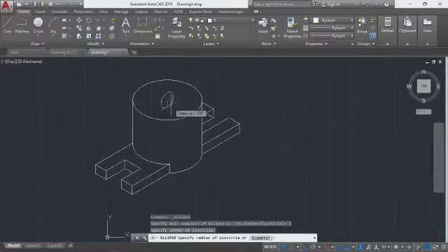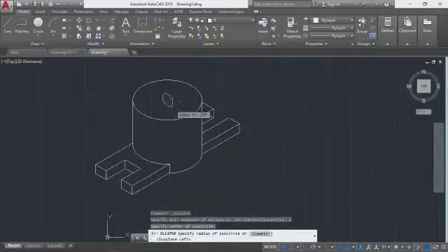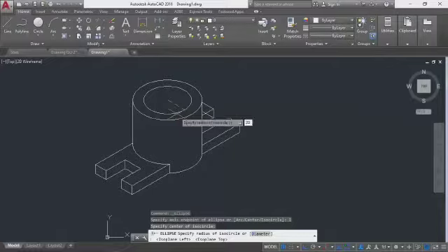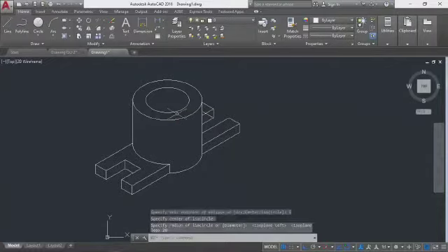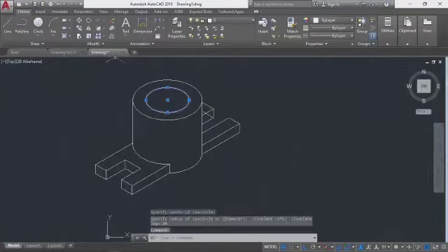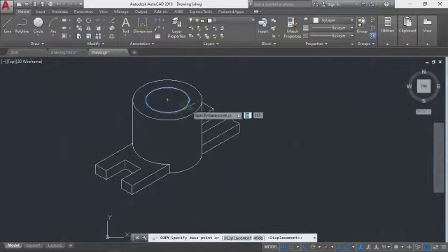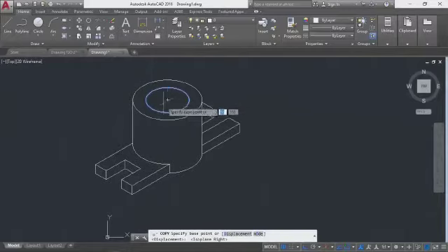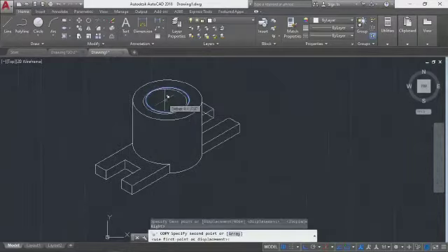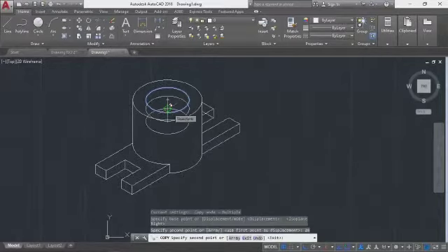So you use your F5 to change the direction. So I've changed the direction. You know, I said it is diameter 40. The radius will be what? 20. So you type in radius 20. You have diameter 40. And you can click on this and now copy to display. You change your direction. You see that? By 24. That's 24 deep. You have something like this.